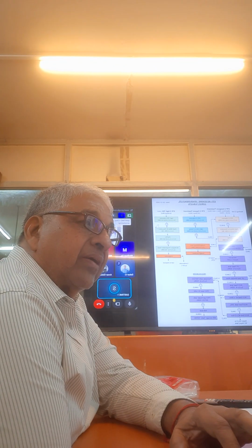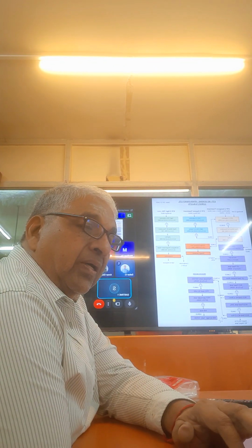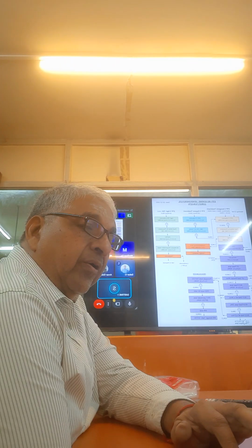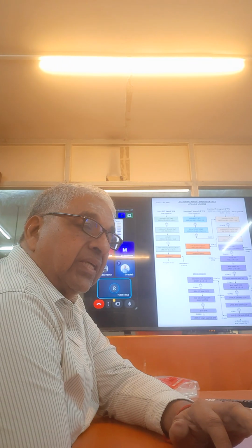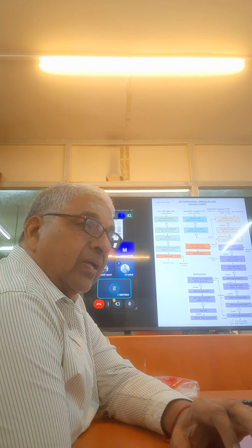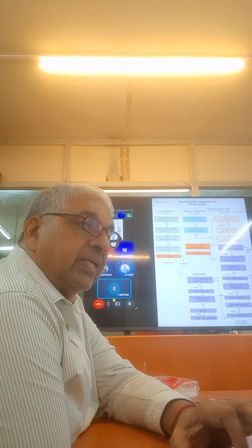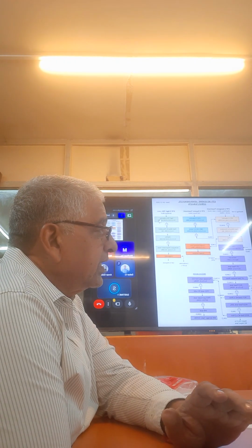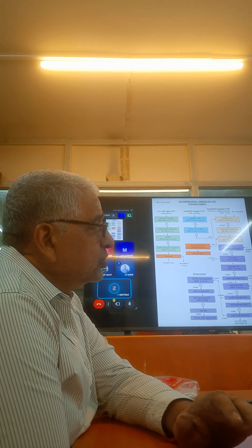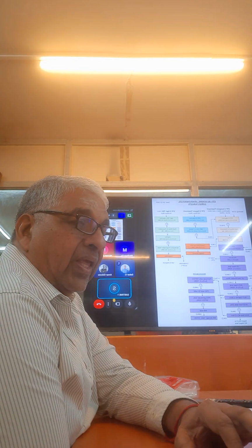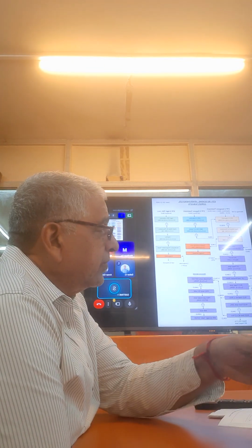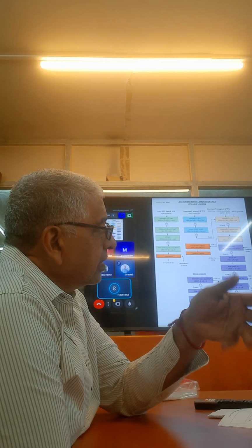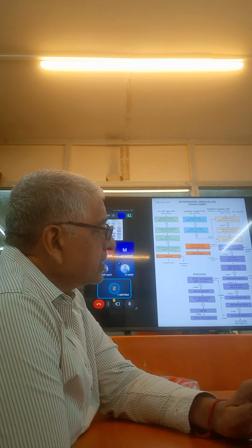But the collection tank will be here. Now I am going to add one more collection tank here for reject. Initially I thought I will take the reject and the dump in the same tank, but I will keep it separately. The idea being, once you collect the RO2 reject, if you have free time, you can even run it again and collect more water out of it by recycling.